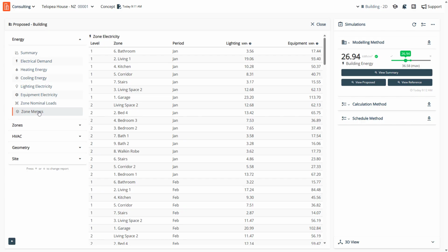So there's a whole depth of information available to you, and this can be taken to the next step where you accept the VM1 and it is what it is and you comply, but then you can go ahead and actually do a copy of this and make this into a real world model with HVAC systems in there and really optimize it to a much greater degree, do overheating analysis for TM59 for Homestar or daylight systems for Homestar, that sort of type of thing.